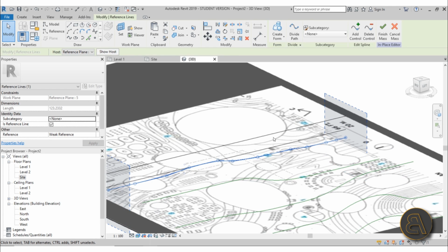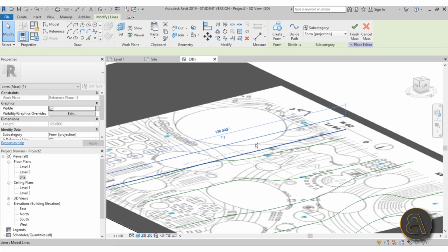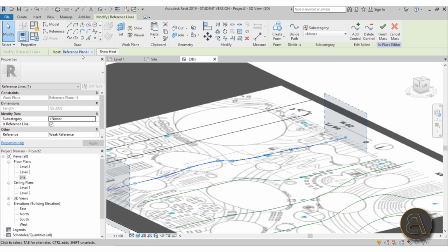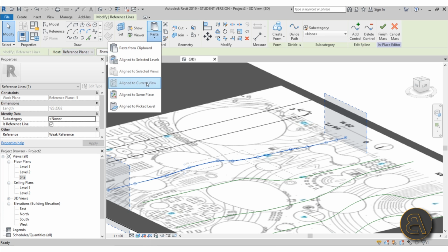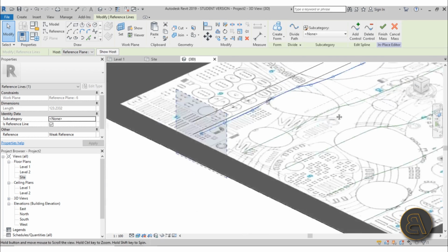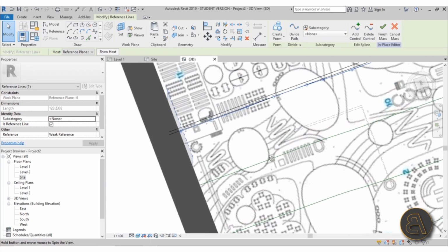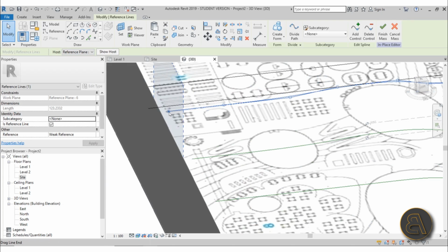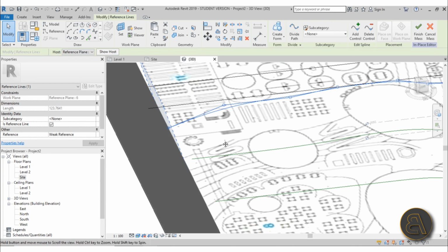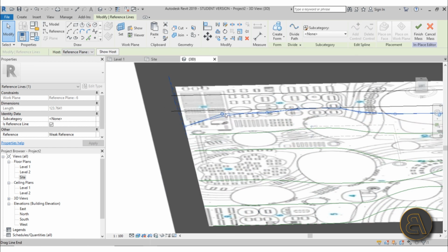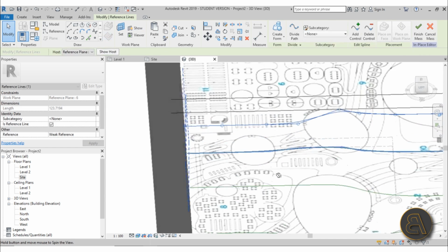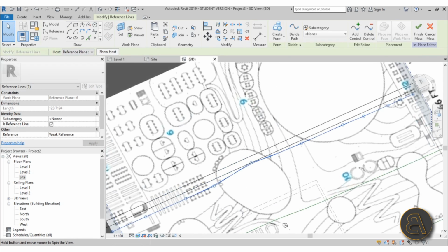So let's select the guides first. Select both of them. I go here to reference plane number 6. Select this one, copy, paste, same place, reference plane number 6, there we go. Okay, so now what's going on? If I look at the contour lines at this end, we're all the way down, so select the endpoint again using the tab to select. Is this all the way down? Yes, it is. Then use these lines, so go like that, and here it's starting to go up, I think.